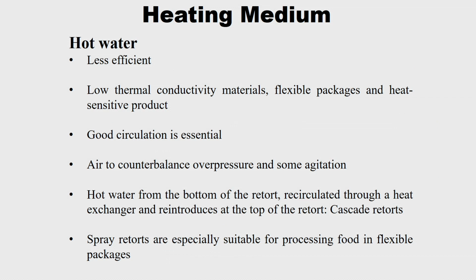Hot water is also another heating medium. Compared to saturated steam, this is less efficient, and where it is favorable is what I told: low thermal conductivity material, nothing but glass. When there is a thermal gradient developed in the glass, which is a low thermal conductivity material, the hot water is outside. So you will not have much thermal gradient between the heat transfer medium and the packaging material. In such cases hot water is favorable, and good circulation is essential.